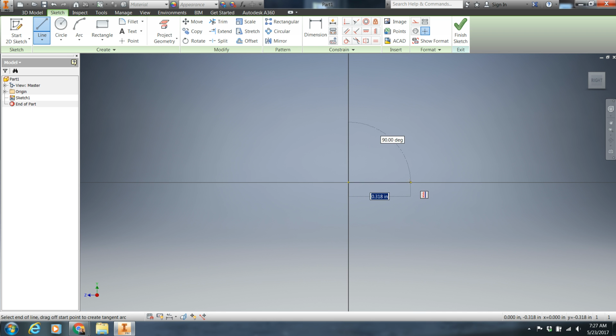If we want to make 3 blocks stacked together, that would be approximately 3 inches. So we would type in 3. Then you hit Tab. You hit Tab so that you can tell the direction you want it to go. If you want it to go up or down, there are 3 options. You can have it go 0 degrees, 90 degrees, or 180 degrees. Make sure you look to see about where the degree is. Notice it says 87.78. You're going to type in 90 to make it flat, and then hit Enter. The key to changing it again is hitting Tab.